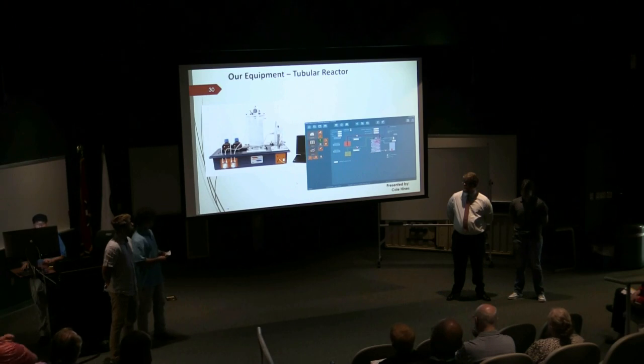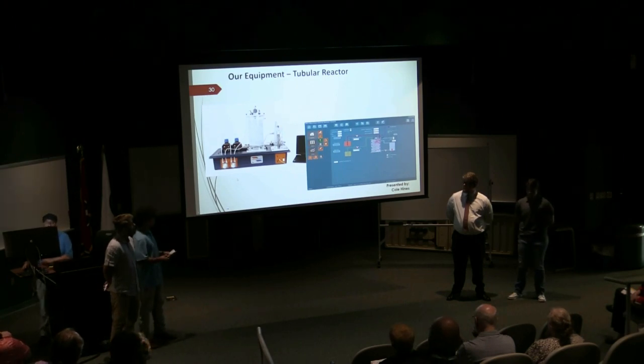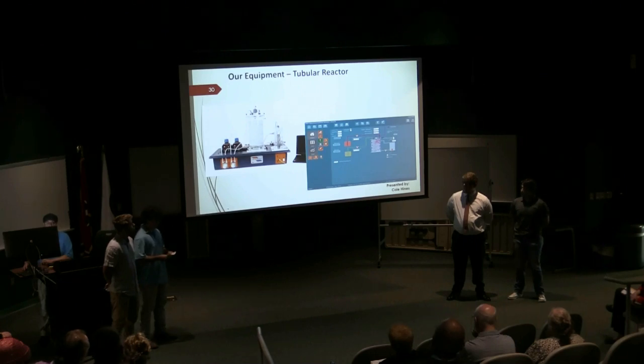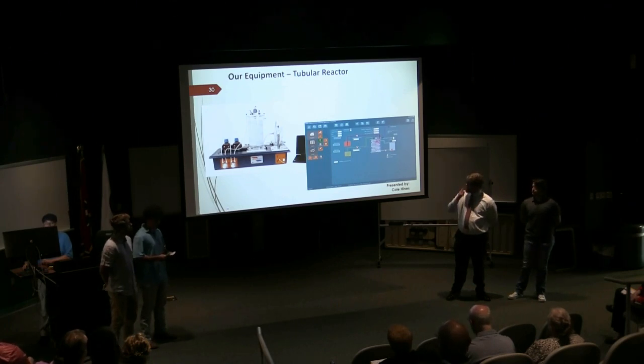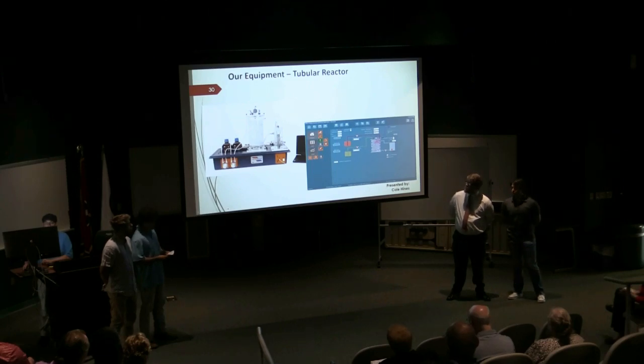And this is our tubular or plug flow reactor. Notice we have two reagent pumps. The reagents flow from their source containers into the reactor and are surrounded by a constant temperature bath. They are mixed at the bottom of this coil right there, and the conductivity at the exit is measured.